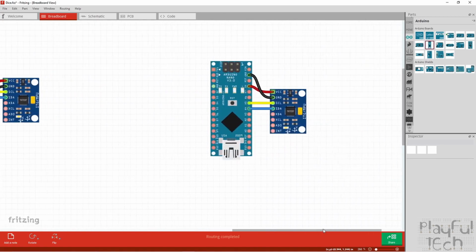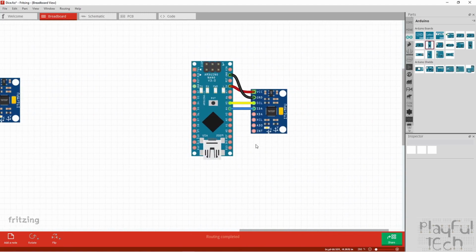Now if that's the case, you can wire it almost exactly the same way. If you've been paying attention, you might find that a little bit surprising, because you think, well, hang on a minute, an Arduino runs at 5 volts. So okay, I've got my ground and I've got my 5 volts going to VCC, which I've told you is going to be stepped down to 3.3 volts here. But surely the clock and the data lines here, well, the Arduino is writing a 5 volt high signal here. Isn't this going to be too much for the sensor board to handle?